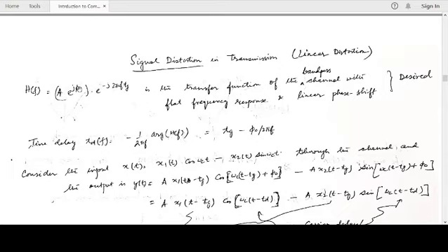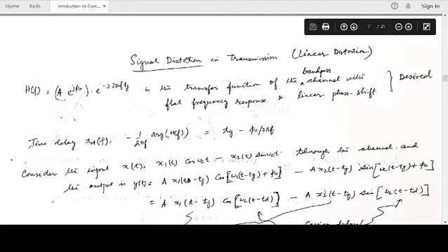While in the case of nonlinear distortion, the signal propagates through various kinds of nonlinear elements. For example, on the receiver side, after receiving the signal, you may have an antenna with some active circuits. The active circuits, for example low noise amplifier, mixer, and other things, are nonlinear in nature. On the transmitter side, you have to amplify the signal a lot to increase its strength. However, a large amount of amplification means you are operating in the nonlinear regime. So you have these power amplifiers, which are nonlinear in nature, and they introduce something known as nonlinear distortion.